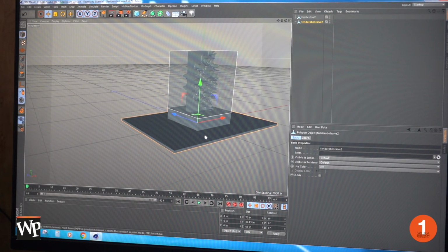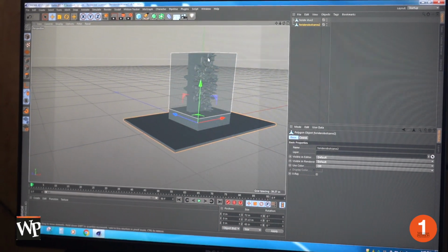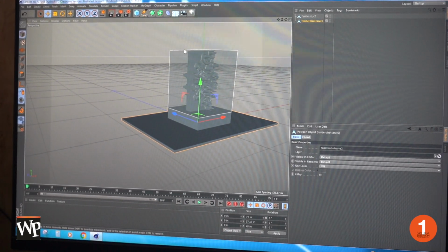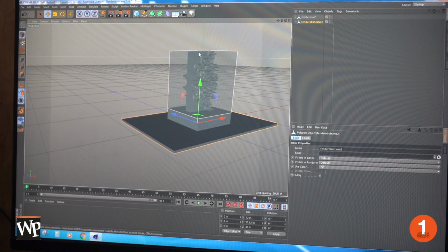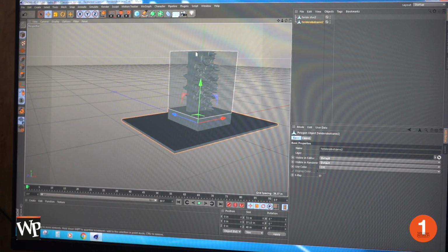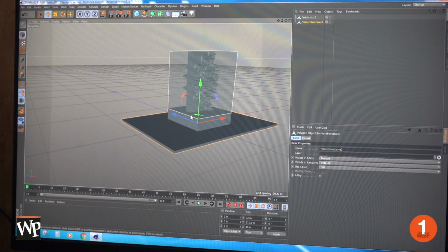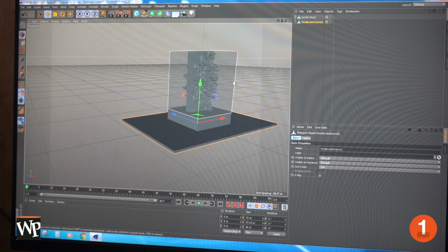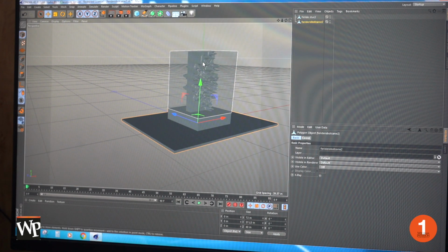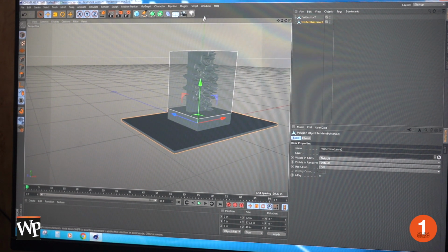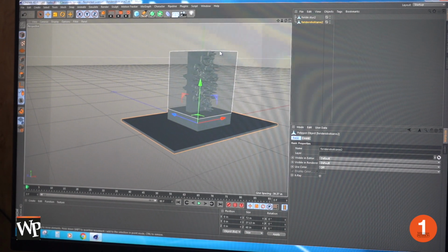So then we place our model inside the block, and then we make another block that's 24 by 24 by 30 inches tall. And this will export as a separate file, and this will be our stock. Our stock is the part of the model that will be carved away in PowerMill.